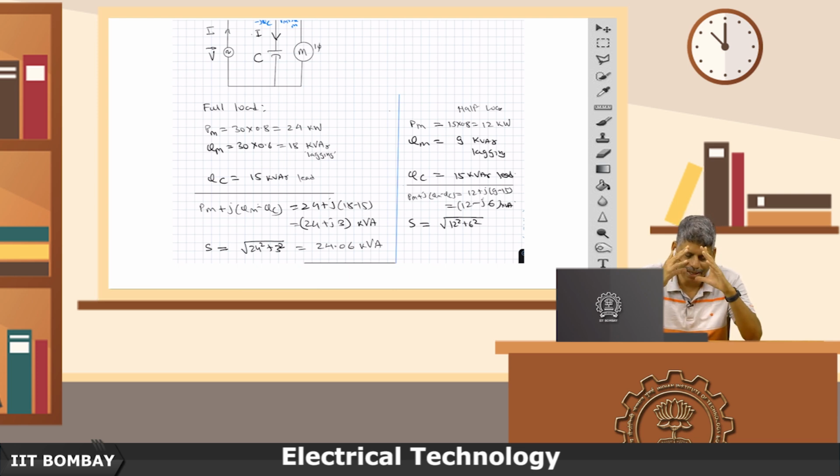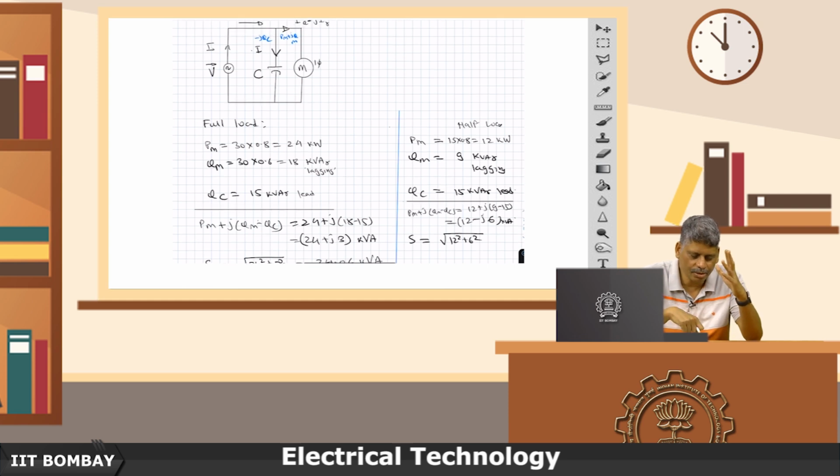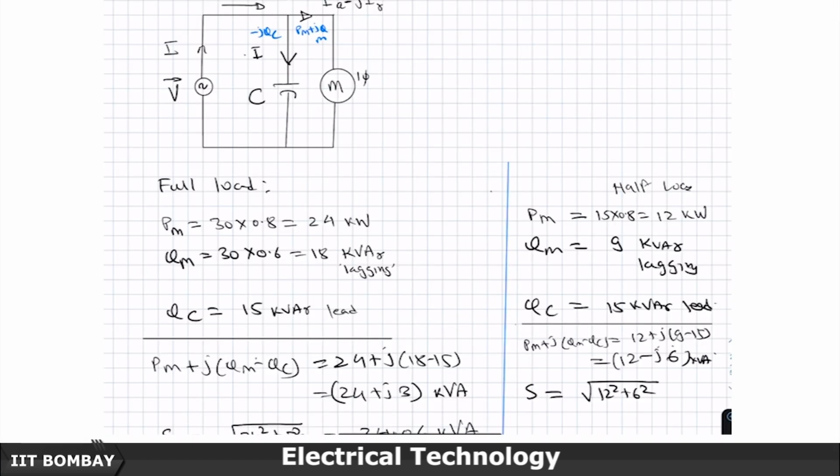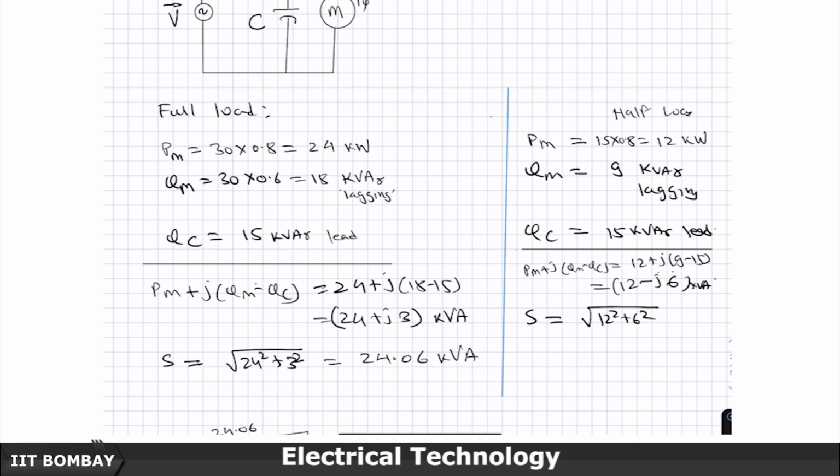The method used here is one common fixed capacitor, but the motor load will keep changing. So, at some point it will be ideal, at other points there will be some deviation from non-ideality, because this component we are not able to bring to 0, but even then there is going to be loss reduction if you have appropriately chosen the capacitor value.